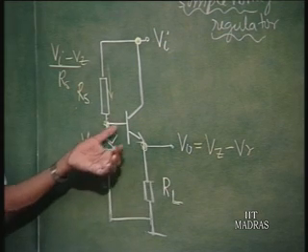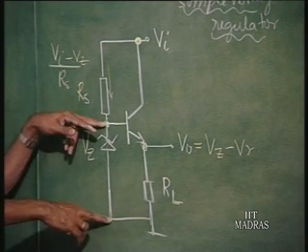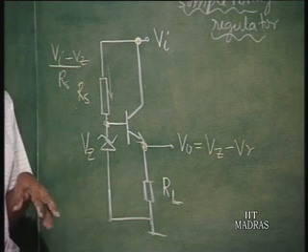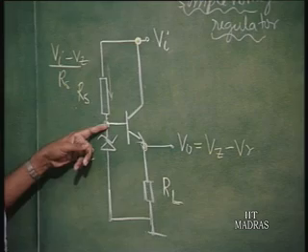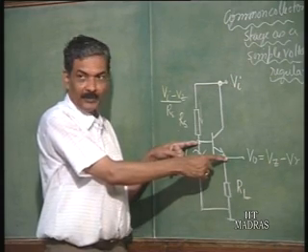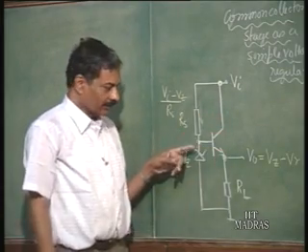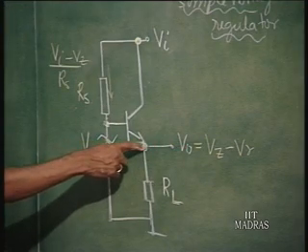So, we put a current amplifier. This is similar to the structure that we had discussed. We have a voltage reference and we have a series pass transistor. We do not really now need a comparator. We straight away use the output voltage and V Z as the input voltage to this transistor, so that the drop across the transistor is controlled. So, this is one input voltage to the transistor, this is another voltage to the transistor.